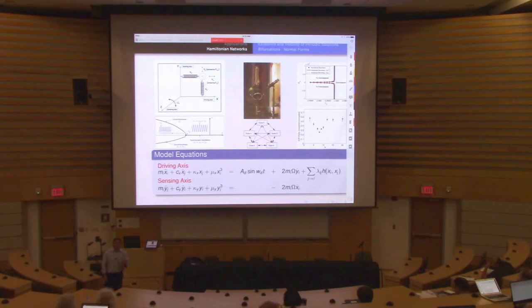In this case, synchronization is important because over the years, a gyroscope degrades based on imperfections of materials and noise, so the gyroscope starts to drift. And that's how people measure the robustness of gyroscopes: how much do they deviate in the angle of detection over units of time? So we simulated and we found somewhere around n equals 8, and this is something that we still don't know why, but somewhere around n equals 8, phase drift becomes very, very small. Then it increases again. So we would like to develop a network of coupled gyroscopes that will operate in this region.